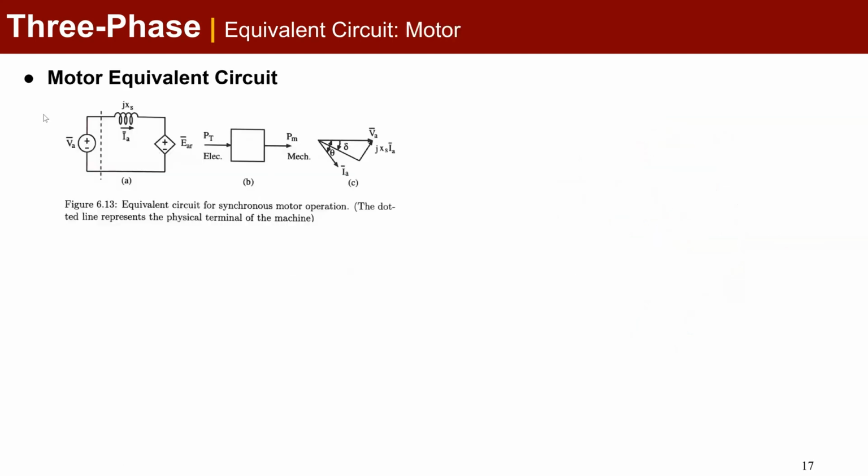So looking at the equivalent circuit for the motor, this is going to be the bread and butter. This is the key right here, that the motor is transforming electrical power into mechanical power, and that equivalent circuit looks like this, okay?